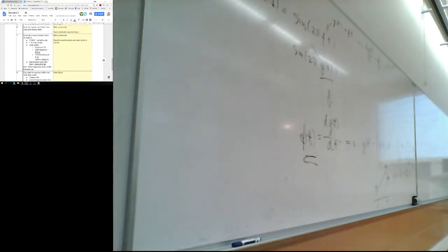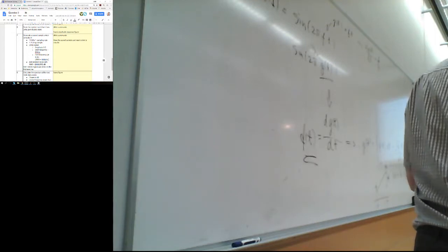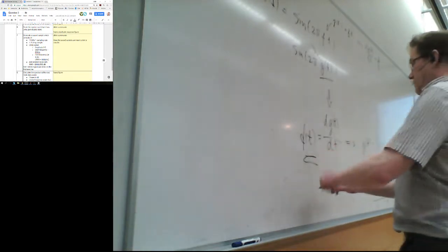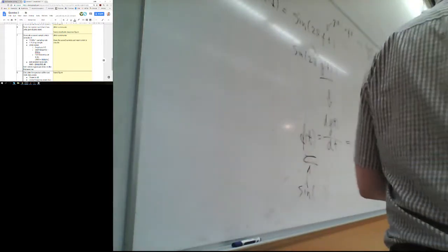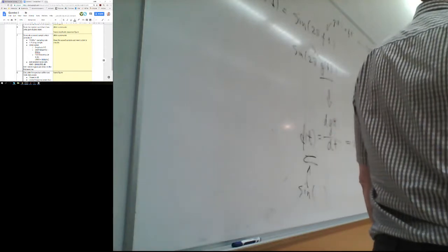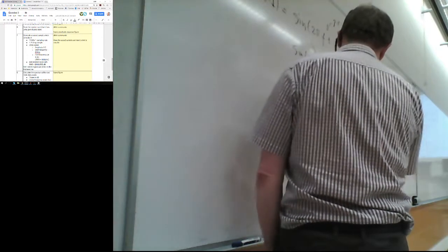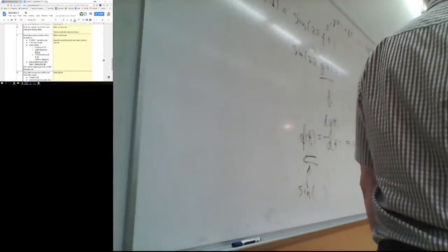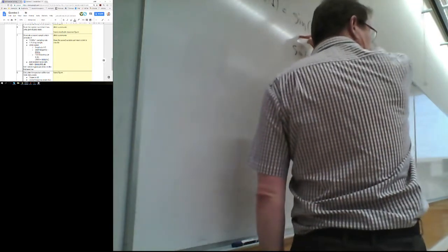But if you want to generate any signal in MATLAB environment, you would plug in that modulating frequency, the frequency you want as g(t), and then do numerical integration, a cumulative numerical integration, and then plug that one inside of sine.